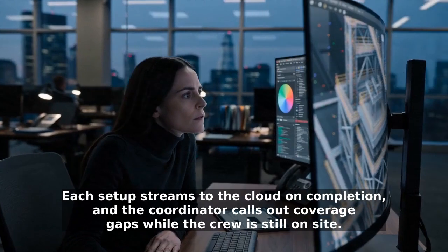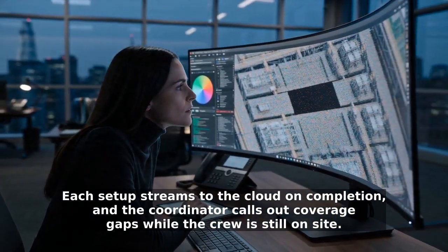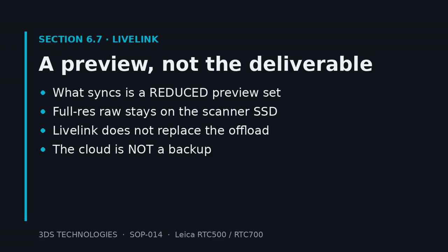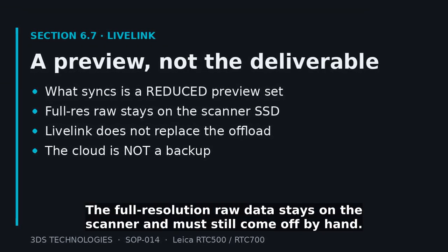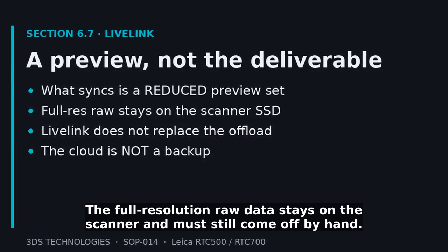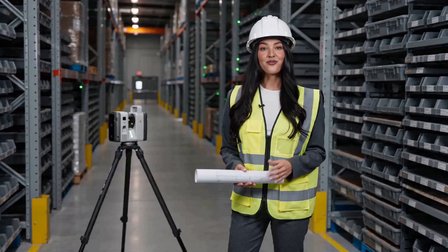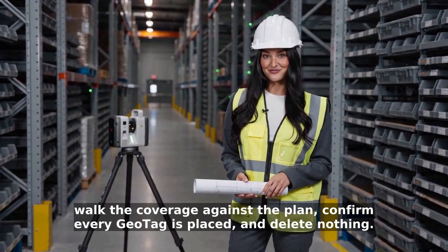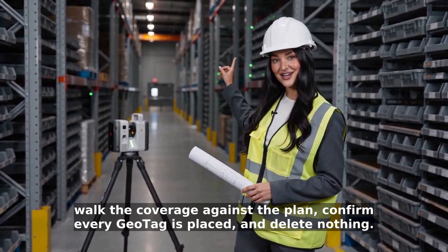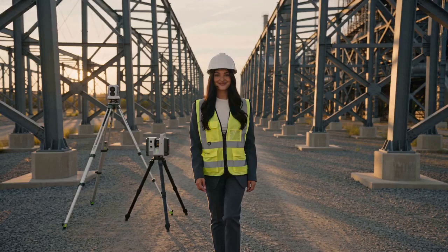Each setup streams to the cloud on completion, and the coordinator calls out coverage gaps while the crew is still on site. But LiveLink is a preview stream, not the deliverable. The full resolution raw data stays on the scanner and must still come off by hand. The cloud is not a backup. Before leaving site, walk the coverage against the plan, confirm every geotag is placed, and delete nothing. Nothing comes off that scanner until the offload is verified.